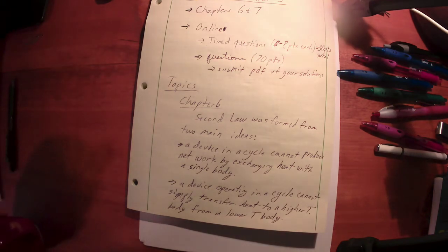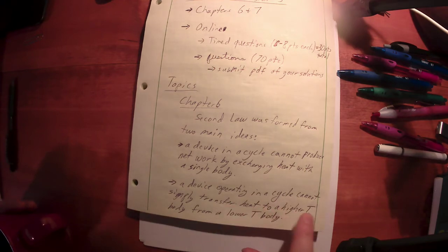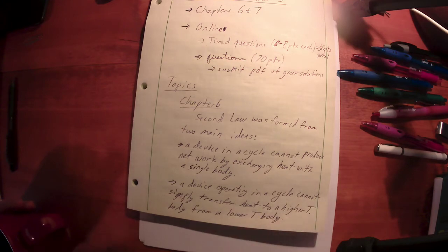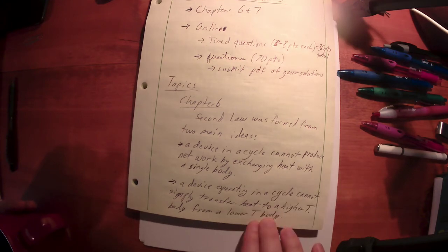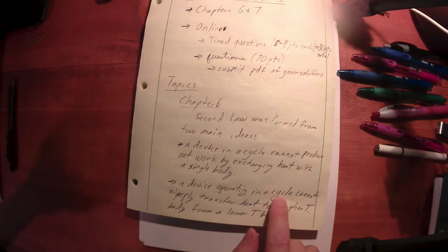What it's also doing is using electricity to run a compressor unit to increase the energy of the fluid stream to a high enough temperature that it will actually move heat into the higher temperature body. And then it goes through a process where that refrigerant gets cold and it'll absorb heat from the lower temperature body, and then it's ready to repeat in the cycle. Okay?